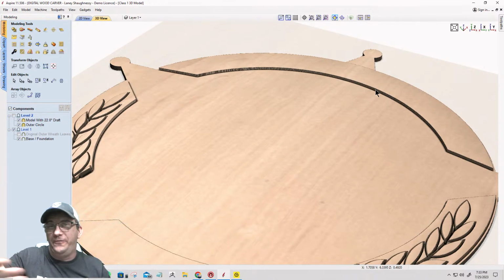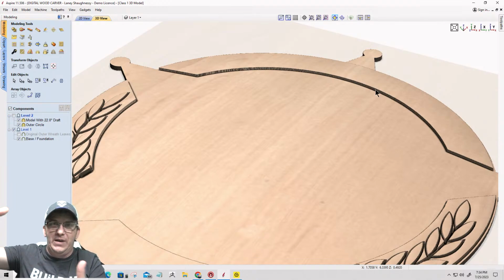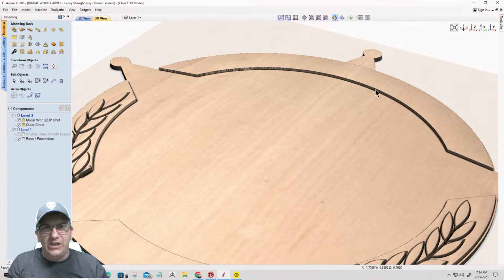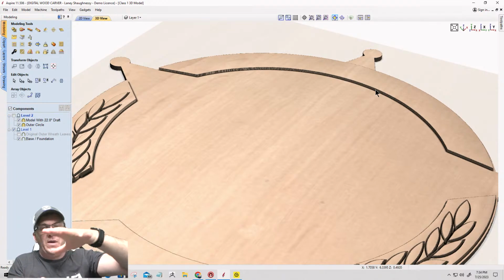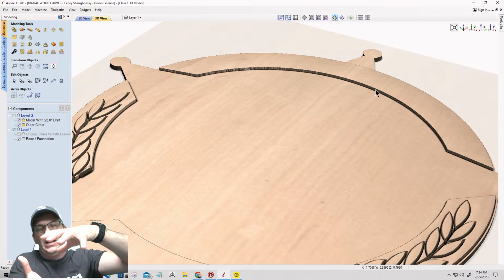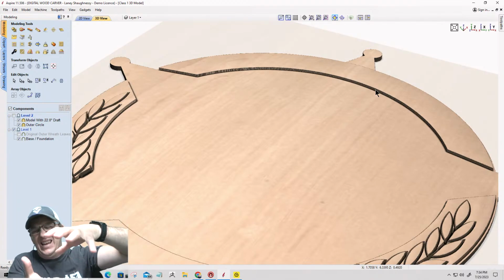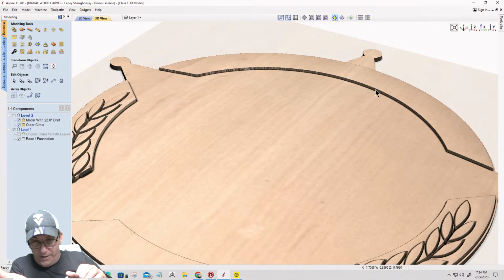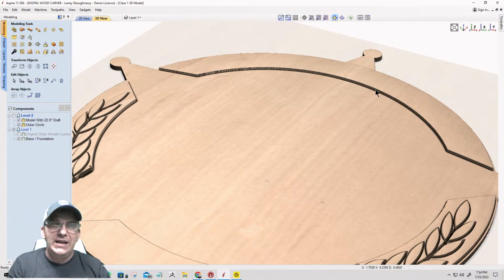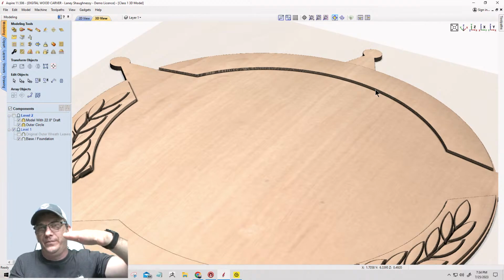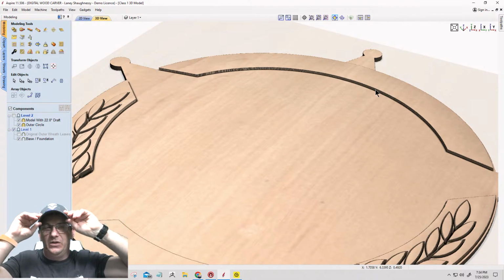It has to be able to still fit in my board that I'm carving, right? Whether it be a 3/4 inch board, 1.5 inch board, 1.25 inch, and all that stuff. I need to have enough wood. Let's say that when this model was all built and complete, it was 2.5 inches thick, from the bottom of the model to the tippy top of the highest component. And let's say that my project board was 1.5 inches thick. Well, the software is going to give me an error that my model exceeds the thickness of my material.